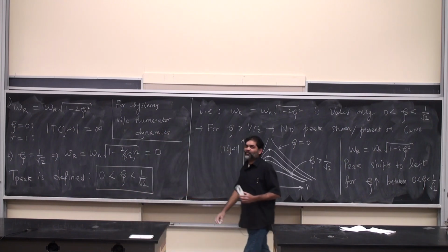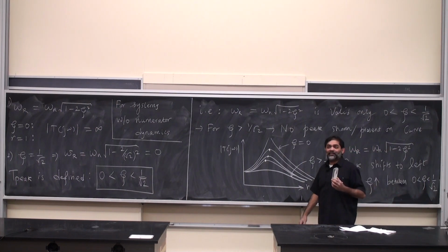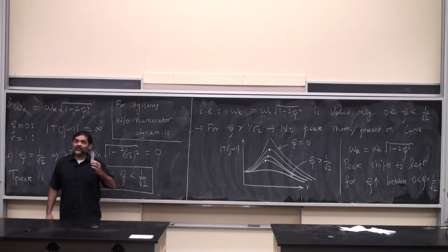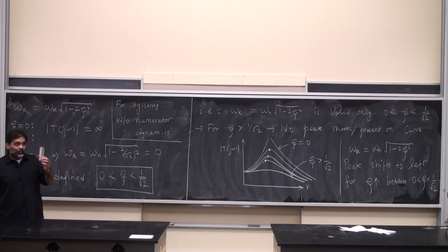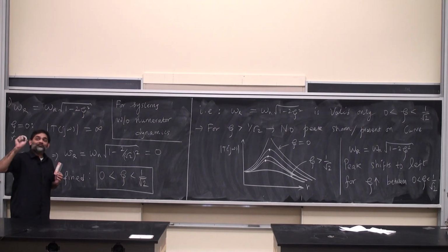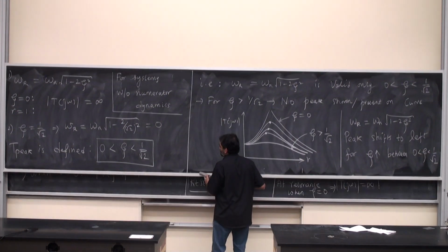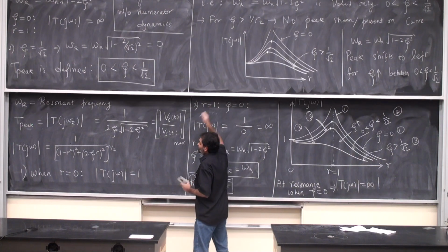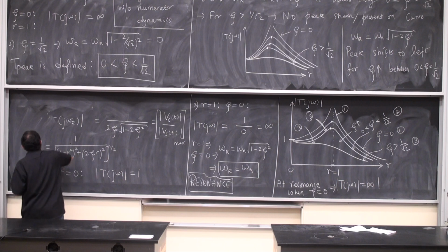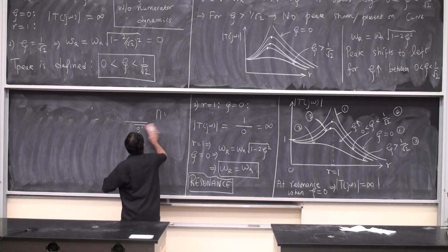What is meant by numerator dynamics is if the numerator itself has some zeros. That's called numerator dynamics. Okay, typically in a system that we are studying here, there are only poles, the roots of the characteristic equation. If the numerator has zeros, that's called numerator dynamics. Not the physical zero, but the definition of the term zeros. Okay? Alright, so that's what I want to talk about here. I want to look at a quick example before we move on. I'm happy to answer other questions. I'll give a brief pause. Questions, of course, related to the lecture.